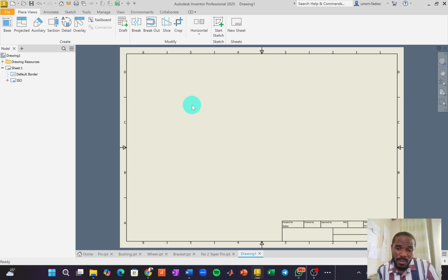That's the figure. That's the shape that you're going to be referring to. The plan is placed beneath the front view. Then the right side of your drawing of your model is placed on the left side of the sheet or of the front view. That's first angle projection.